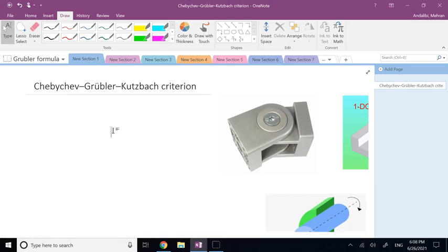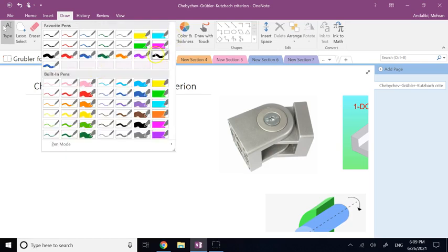It says, let's say I have n rigid bodies, and one of these n rigid bodies in my system is grounded. It is connected to the ground by any method, which we might also call a rigid joint or a rigid constraint. Like we have welded it down to the ground, we have bolted it, we have used any method of rigid connection so it does not translate or rotate. So the degree of freedom for that is 0. So if you have n rigid bodies in your system, with one of them being the ground member, correct?